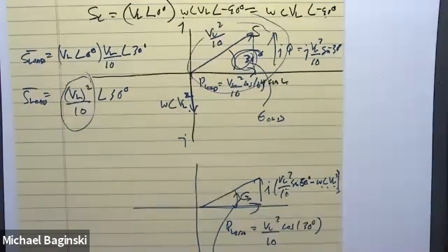I'm going to give you more information. That's the goal of industrial engineers when you are running a power plant. You would like, at all times, the reactive power to go to 0, which means the power factor would be 1. You've done power factor problems in industrial engineering, right? I know you have. I see your heads bobbing there. Yeah, that's the goal. That's really what happens when you put a capacitor in parallel with a power plant.